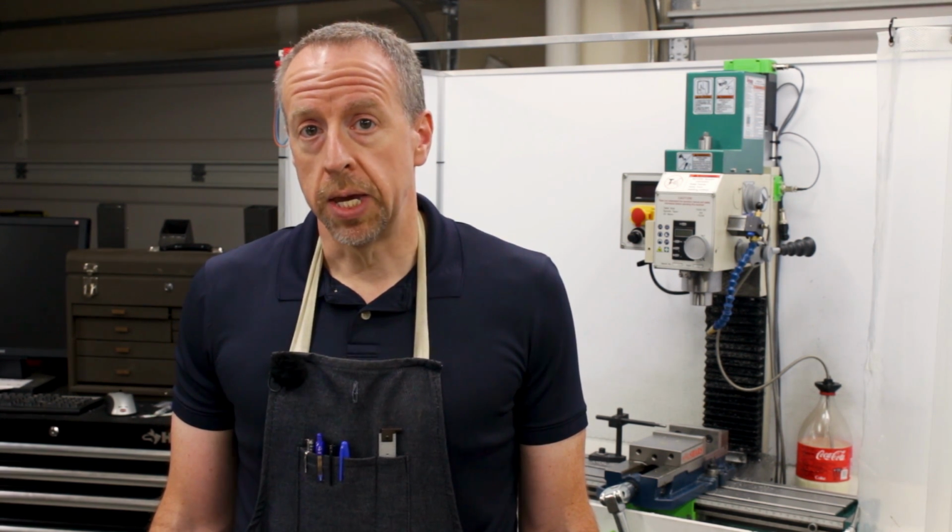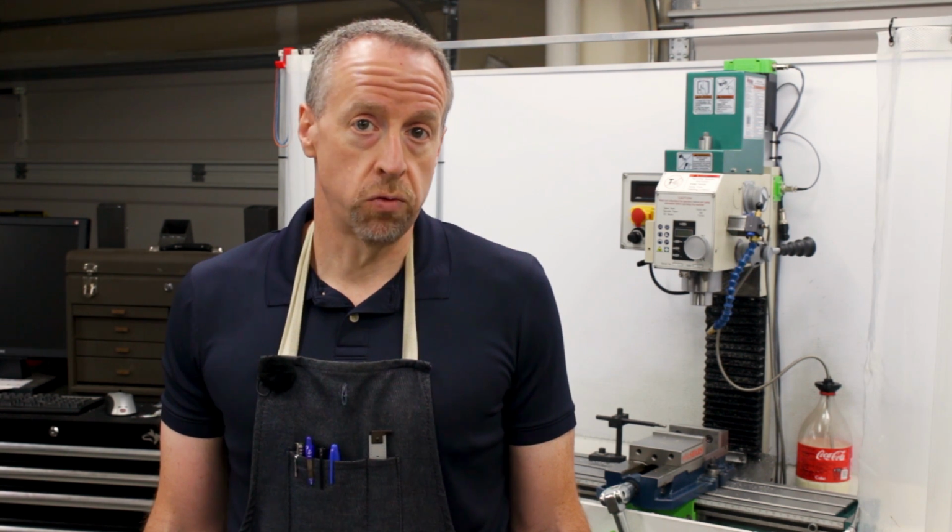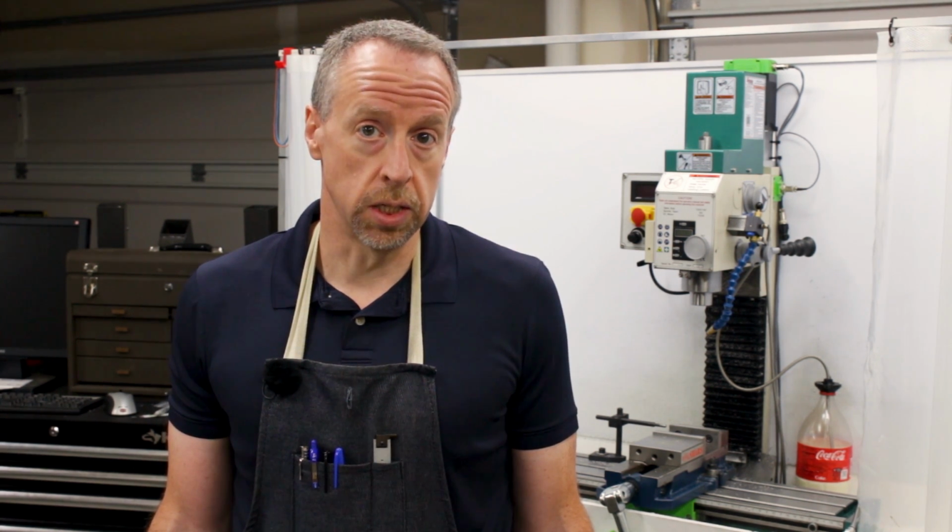One of the questions I've been getting a lot is whether I am going to support lathes with metric lead screws. And that's something that I've always intended to do. It's something I designed for from the beginning, but it's something that I haven't gotten to until now. If you check the code on the GitHub repository, you will see that I have now added support for metric lead screws. And today we're going to take a look at the calculations, take a look at the code, and walk through how to set it up for your lathe.